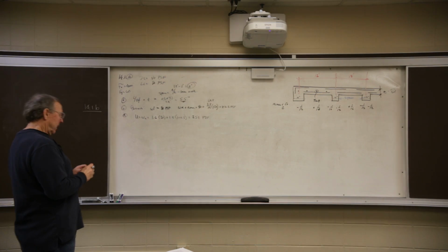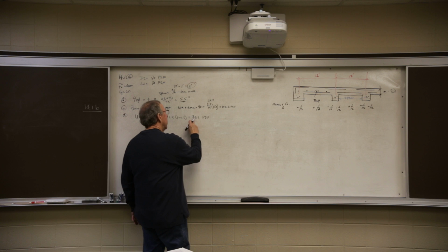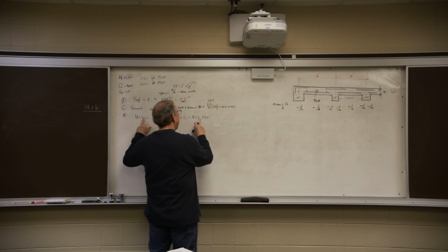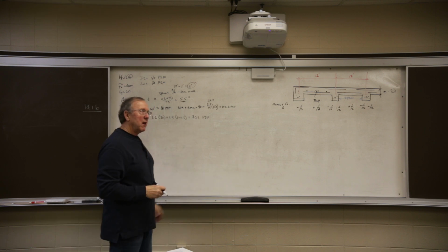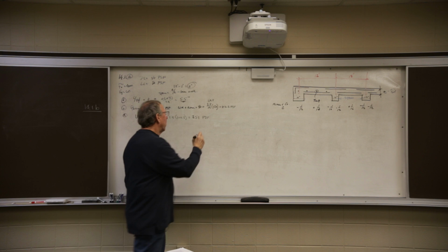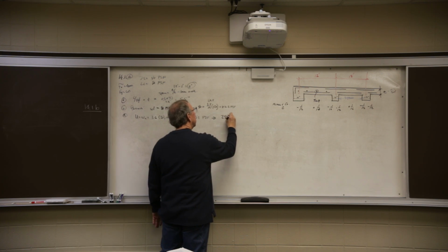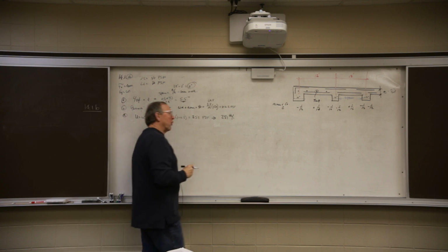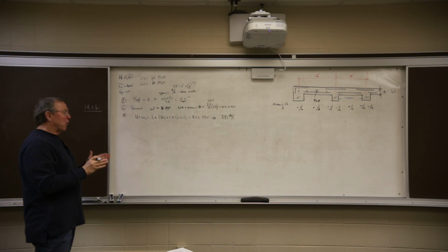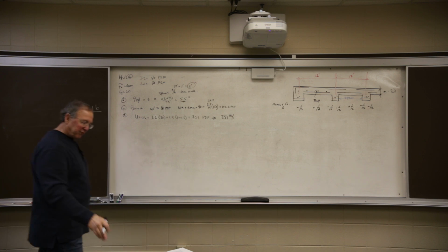Okay, same logic as in the simple slab. Little w is supposed to have pounds per foot, and I have pounds per square foot. We have a 1 foot wide strip, therefore this can be done fairly easily. The only reason it can be changed is that we've got a 1 foot wide strip. Okay, so there's my load.